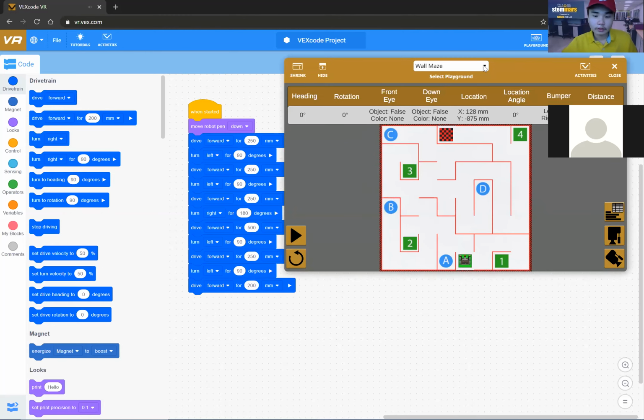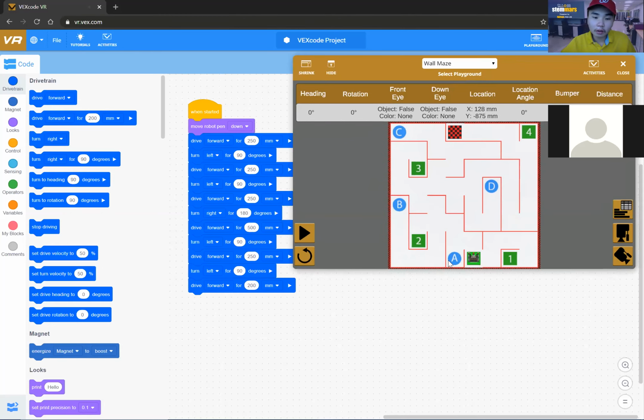All right, so now that we have that move forward 500 millimeters, it works. So let's just copy paste, because this path right over here is the same as this path over here, correct? It's the same exact distance. So let's do 500. All right, reset, play. Let's see how that turns out. Oh, you also see the green, it flashes in your code over here. That means that's the step the robot is at. It also analyzes every single step you have.